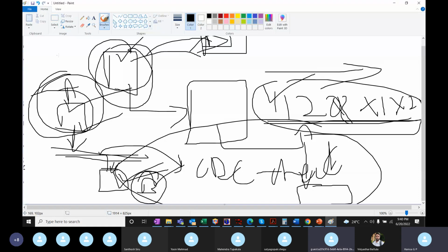Similarly, if this ECU is sending the data to the BECU, the BECU has to acknowledge that I have received your data. Otherwise, ECU-A will not understand whether anyone in the node has received my data or not. If someone is acknowledging, then only ECU-A understands, okay, someone received my data. Otherwise, nobody has received my data. That is what is called acknowledge. That is what is done by the acknowledgement field.